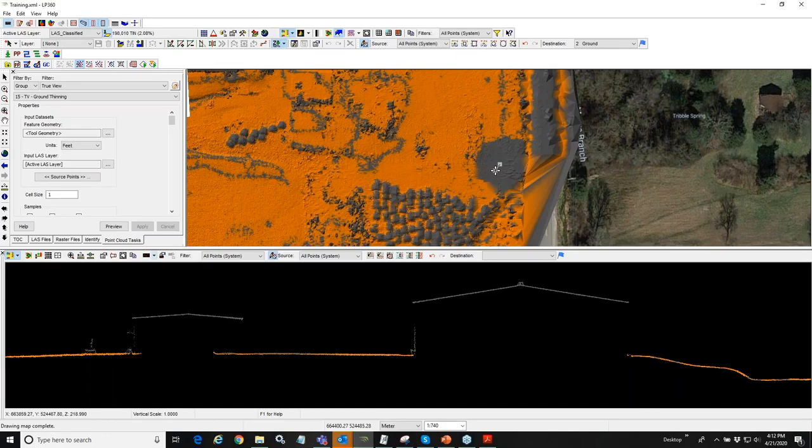My main point is I wanted to show you there are tools that you can use to do the cleanup, and you should expect to do a little bit of cleanup, especially the more complex the terrain is that you're surveying. If you have a lot of forested areas, if you have a lot of relief in your topography, if you've got a lot of buildings, large and small, the more complex the scene you're scanning, the more you'll expect to do a little bit of cleanup on everything.